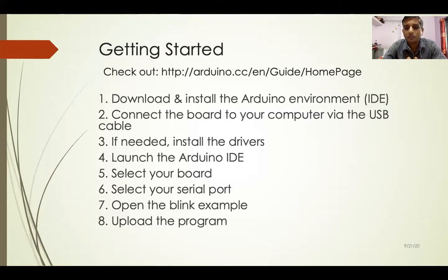The free port is allocated to your hardware. You have to select that particular board. Now, how to check that that particular port is for your Arduino? For that purpose, you have to check it by removing that cable. When you remove the cable, that serial port is gone. When you insert it again, your serial port is there. So you have to check which port number it is, and you have to select that port before uploading your program.